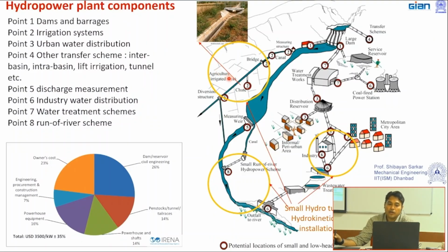So this type of hydrokinetic, and since you have seen hydrokinetic so far, I have shown you some pictures, Sir must have shown some of the pictures. So the hydrokinetic turbine is a very simple device. For this particular device, you require clean water and fast water. So if this type of man-made canal is prepared, we can put some strainers so that we can arrest those impurities in the upstream, and then you can allow the water to pass through this particular area. So these particular parts are very much suitable.